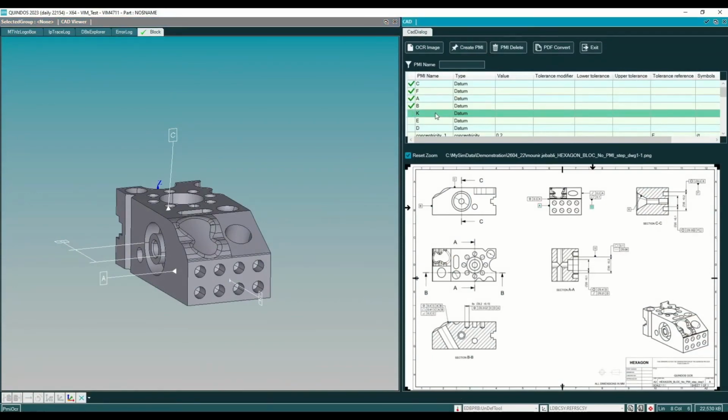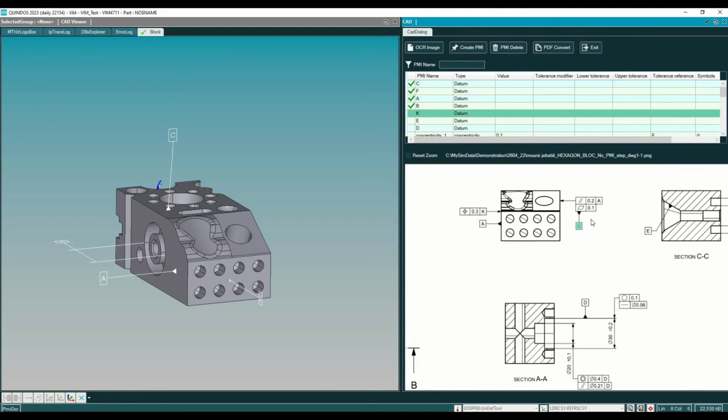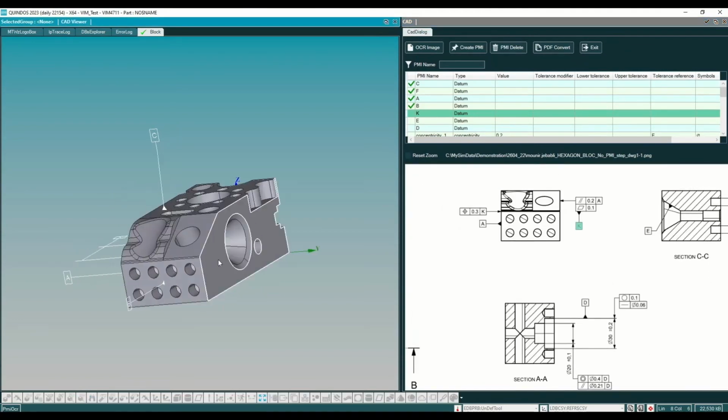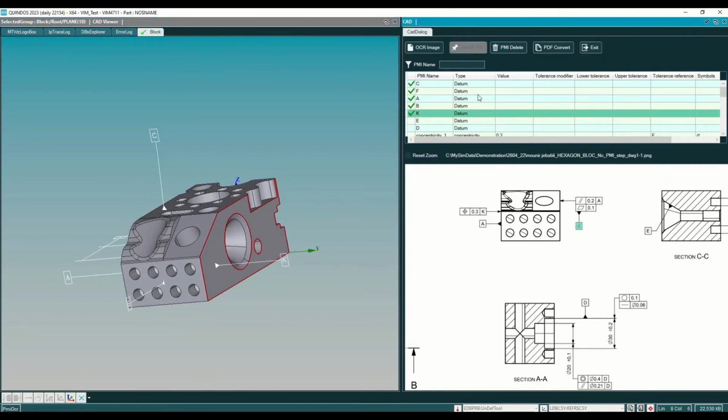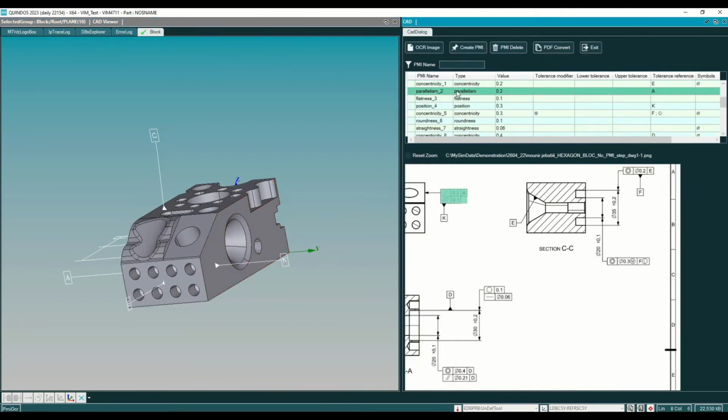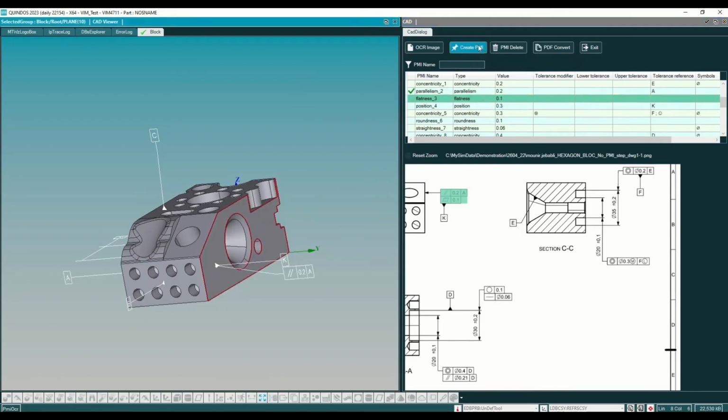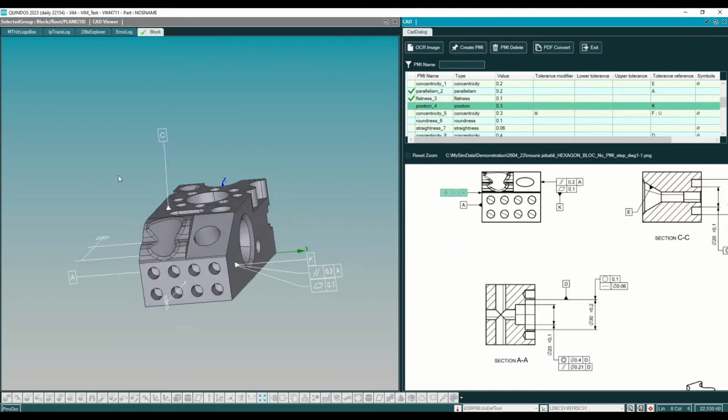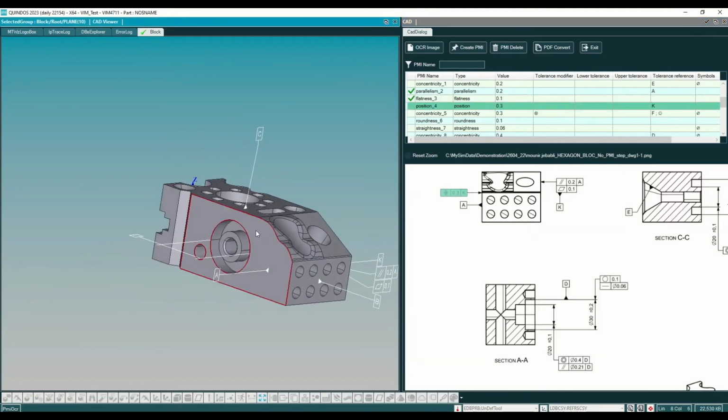Then a lot of customers are asking about legacy data, and they're still using 2D drawings. They have no time, especially the design departments, to rework all their CAD models and attach PMIs now for the metrologist. Here we can use optical character recognition to parse your 2D drawing and provide all the PMIs as a list, and then you can add the PMIs to a list on your own directly on the machine. Afterwards, it's the same process. You can use these PMIs to generate your measurement program.